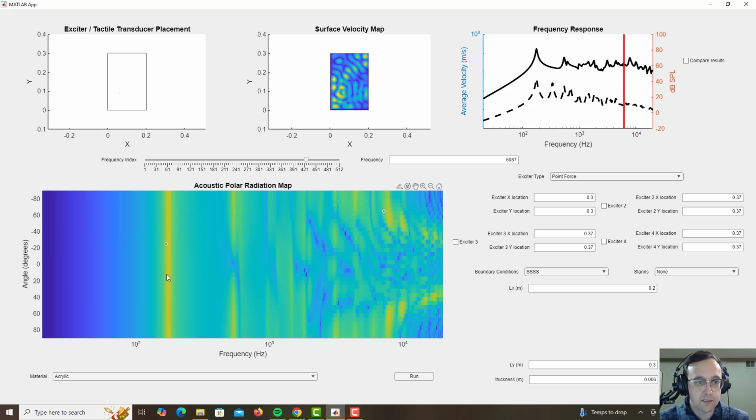Yeah, so this bright line here corresponds to this mode at 174 hertz-ish. Let's go find that. That should be, yeah, this guy. So that's this mode, and that causes this bright line here. This funny pattern right here is at, what, 541 hertz? Let's try to find, does that correspond to anything here?